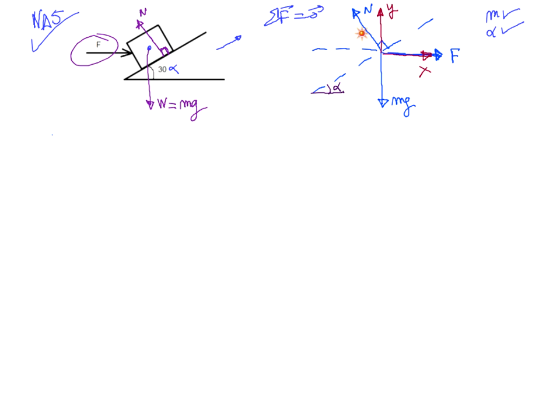And that's where I'm stressing that the free body diagram needs to have those three components: force label, coordinate system, and direction. Because if you skip the direction part, how are you going to express n? No idea. And it's not trivial to figure out where alpha is. So think about this and let me know, where is alpha? Is alpha between n and y, or is alpha between n and x?